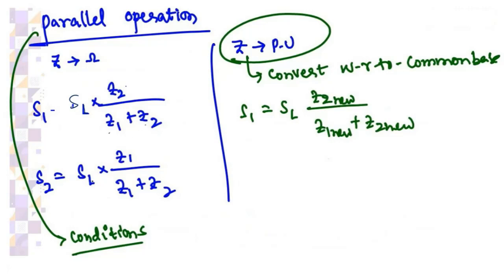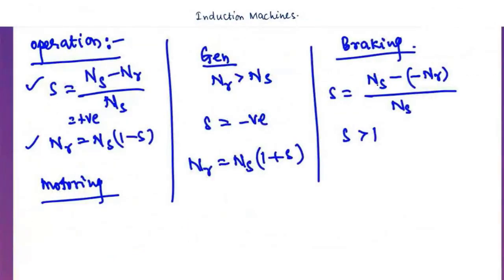So I2 is equal to the entering current times the opposite resistance divided by the total resistance. The same way, it is similar to the current division rule. If they give you the Z in per unit value, please be careful. Convert the per unit impedance according to the common base value and then go ahead. So those are the important formulas from the transformer.